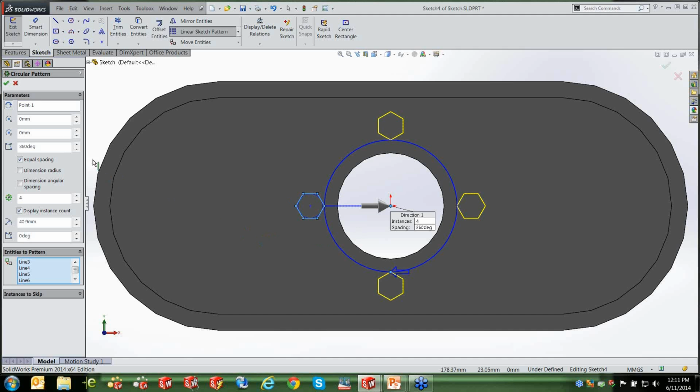Now let's go through some of the options that we have here, because this is really where the power comes into play. First of all, the angle value that you see is the number of degrees that will participate in the pattern. If your pattern is only 180 degrees, you would put it as 180 degrees. We also will have control, even though we've specified a point, we can actually physically move that point using these two options here with the X and the Y.